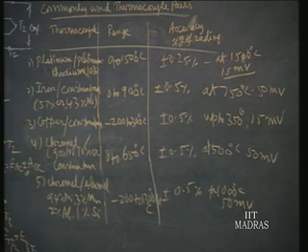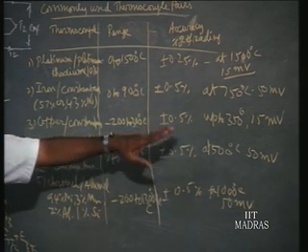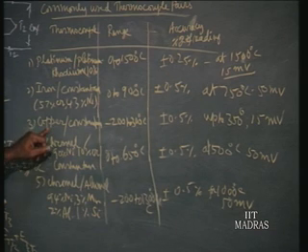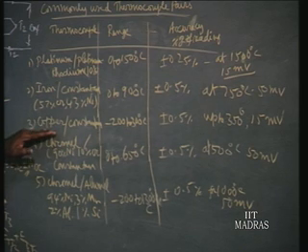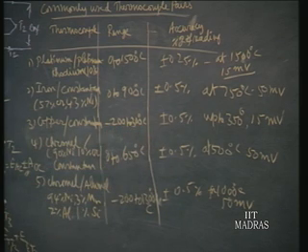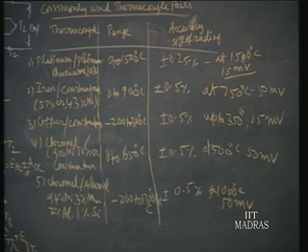It does not get contaminated. Whereas you find the copper constantan can be used only up to 300 or 350 degrees centigrade, that is this range. Beyond that, the copper gets oxidized, so the calibration is lost. It is supposed to be pure and homogeneous material. When it is contaminated beyond 300 or 350 degrees centigrade, then you cannot make use of it. So it has a very limited range.